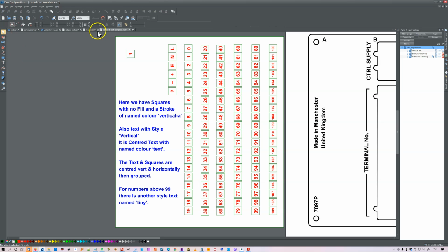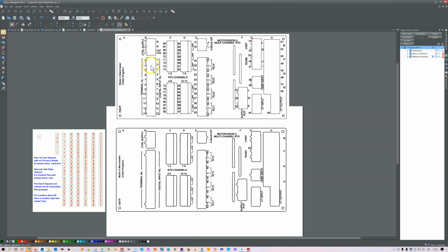So how can we use this? Right, we want the previous zoom. Okay, so just this reference bitmap here. Let's just put these 1 to 12 down there. So I go along here and I select 1 to 12, and what's important is that I hit Control K to clone that, then I Control Alt and move the mouse, take the finger off, and I can move this around as I want, and I'll put that there like that.